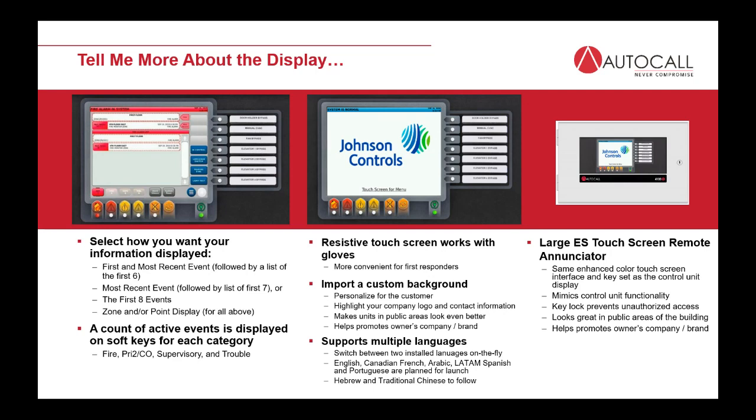The touchscreen is a resistive touchscreen technology, which allows it to be used with gloves, which is often a concern with the fire department. Am I going to be able to operate this with the gloves on? The resistive touchscreen technology is the only one that allows that. So we've used the resistive touchscreen technology for the ES touchscreen display, so we can support that requirement.